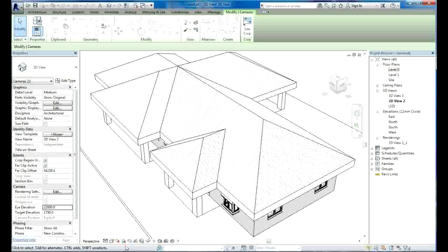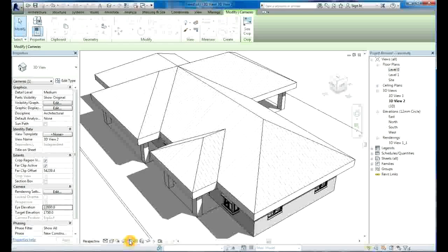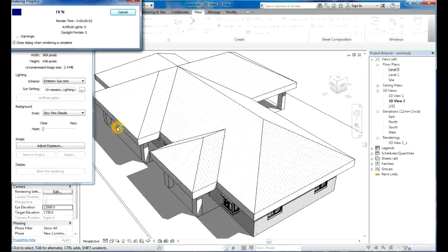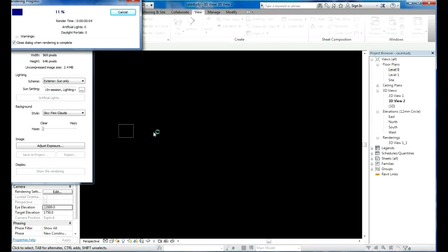and all I need to do is come back here, put the shadows on again, click on the render dialog box, I'll go to high, and then I will render it, and we will come back again when it has, or when it's either well advanced or when it's finished, depending on how long it takes. It will take some time again. So I'll just come out again, and then I shall come back once it's very advanced or nearly finished, or even finished.